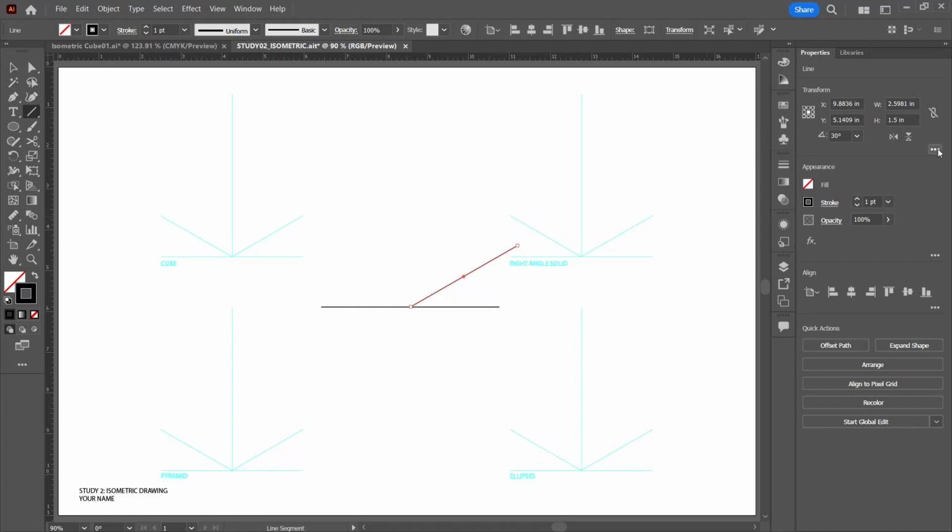You have to get used to not looking at that. If we click our little ellipses here, we can see our actual line length, and that's 3 inches. That's where you can double check what's going on, and there's our degrees. It's a 30-degree line at 3 inches. So just remember that, okay? That's in our more options here.